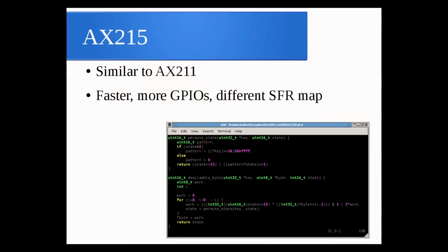There's one really important difference: they got a little bit smarter and obfuscated their code binaries that were stored in the things that would be used in the factory programmers. But this is the whole routine that they use for obfuscation. They came up with, I don't know, crazy, it doesn't even look that good, kind of byte shift swizzle kind of thing. But we can just pull it with IDA and get it to run.